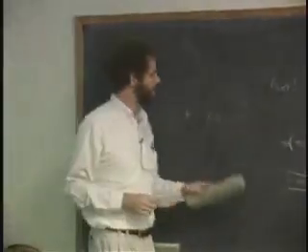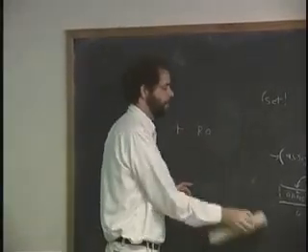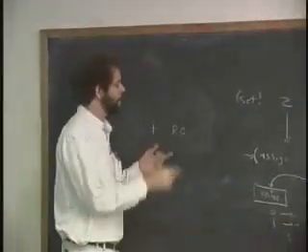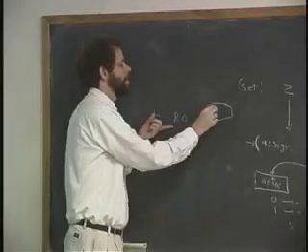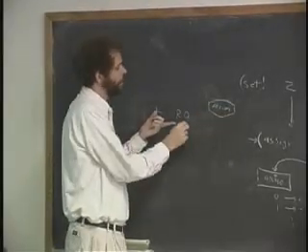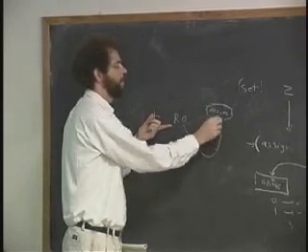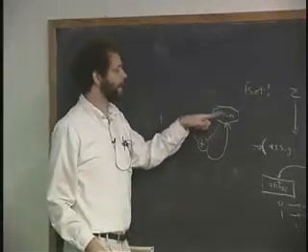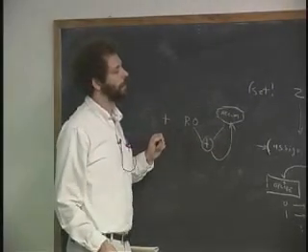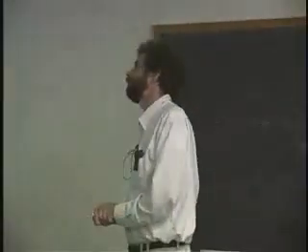Absolutely right. So again, as with the case of the condition register in the Scheme textbook, this implicitly talks about having a register off to the side called the accumulator. What it would do is add R0 to the accumulator and put the result back into here. So you get to choose what got added in, but the memory it got added into was always the same. And then you would again have instructions for pulling things in and out of here and putting them into the big memory. Okay? So the 68HC11 is like that.